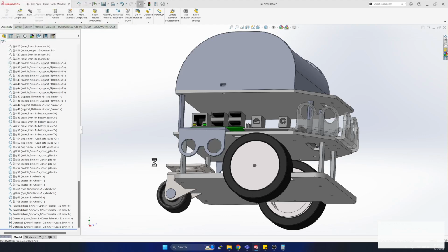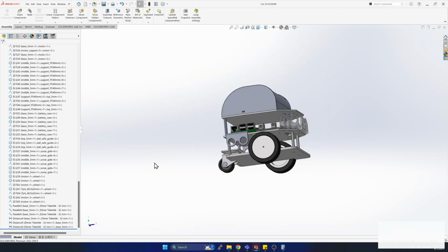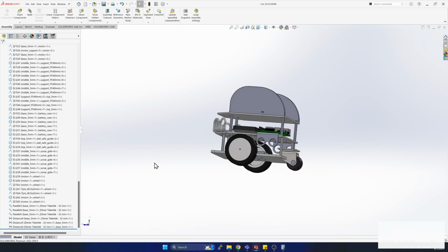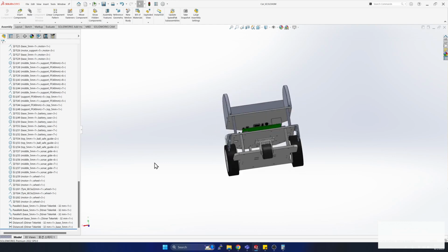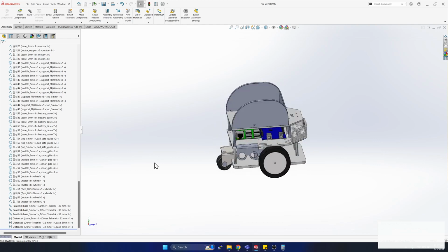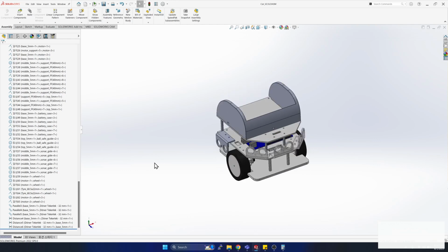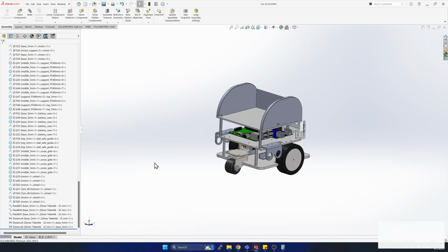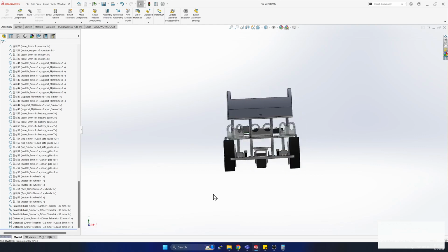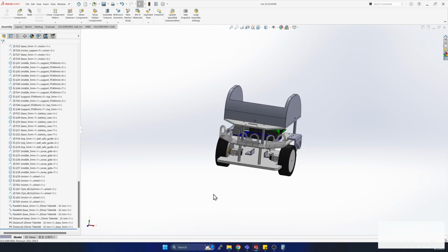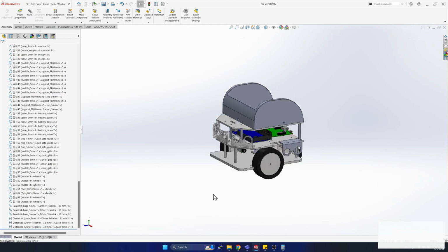Okay, so now, as I understand, there will be 4 parts or 4 links. These 4 links will be the left and the right wheel, the base link, which is this whole chassis, and then this caster wheel. So we basically need to define the axis, coordinate system and origin on each of them.